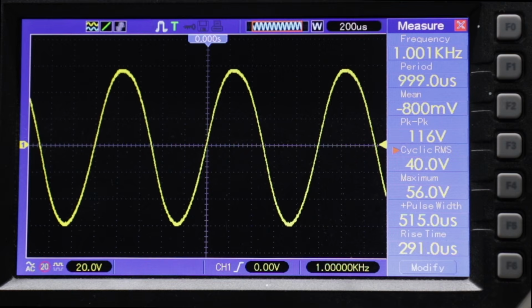This is after the second gain stage. The gain at the moment on the gain pot's pretty low, it's dialed right down. Now, what we want to demonstrate here is how the three different cathode structures give you not only a different gain amount, but a different characteristic of the gain, particularly the 10K. The 10K cold clipper is really what I want to demonstrate here.